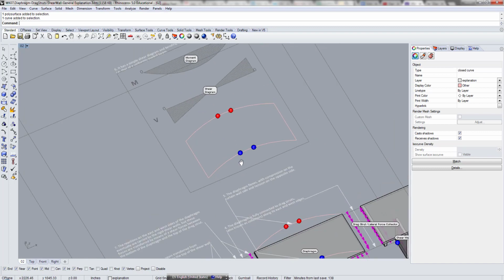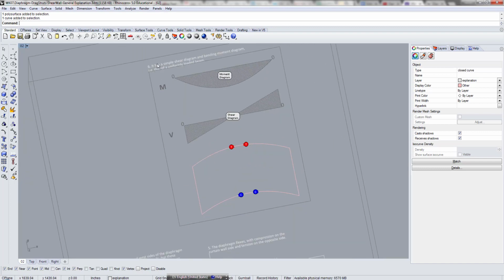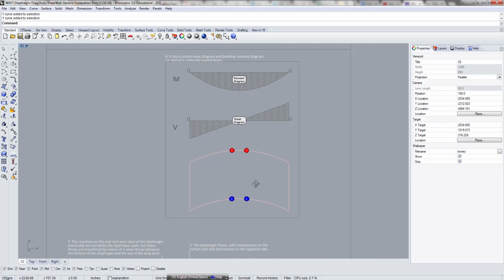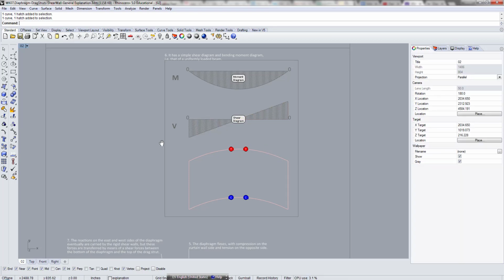Okay, so this isn't super important, but if you look at this simple flexible diaphragm, it's pretty much literally just like the beam, and you can conceptually draw this moment diagram and shear diagram, if you remember these for a uniformly distributed load for the beam, right?